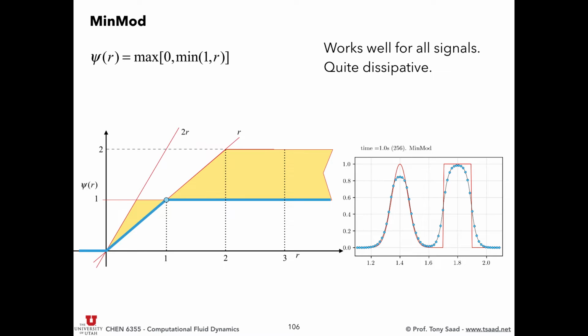If you don't go through 1, you're not going to be second order. So this one picks the lower boundary. This is second order upwind, and then it goes central, okay? Now this scheme is going to be very diffusive, because once we go central, we know we're going to start developing some dispersion. So it is going to switch immediately to this point, okay?